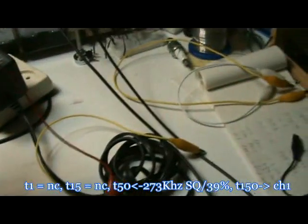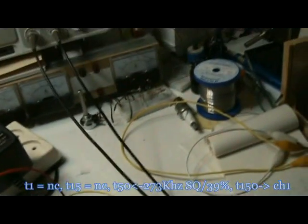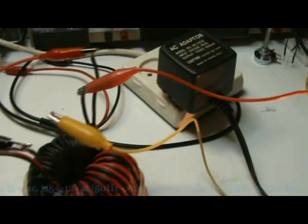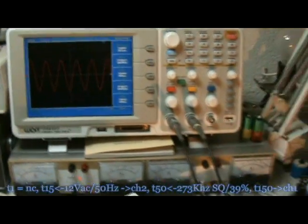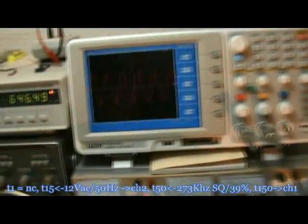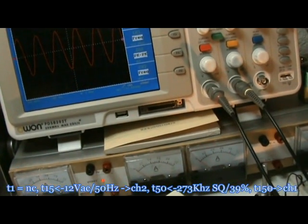So I will put my 50 hertz, about 12 volts peak to peak, with my bulb in series on the 15 turn coil. The bulb gets lit. It protects my transformer. And now at the output I want to measure the 50 hertz.